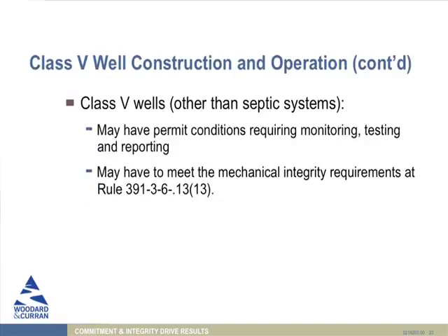Class 5 wells, again, may have permit conditions that require monitoring, testing, and reporting. That will be dependent upon once you apply, they'll take a look, see what you're injecting, what the conditions are, and then decide from that point. You may have to meet mechanical integrity requirements for the well design.